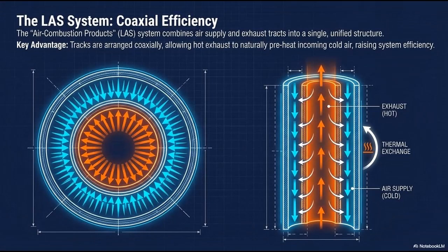But here is where we completely sabotage ourselves. Oh, yeah. Let's say I have that powerful Type B boiler in my basement, but I just spent $20,000 on brand new, highly insulated, double-glazed windows. I weather stripped the heavy exterior doors. You seal the envelope. Exactly. I effectively wrapped the entire house in a tight plastic bag to save on my winter heating bills. So when that boiler kicks on, it tries to violently inhale 100 cubic meters of air, but the room is locked down. It's practically a vacuum. Precisely. You've choked off the supply. And it is not just the passive sealing of the house that creates the danger.